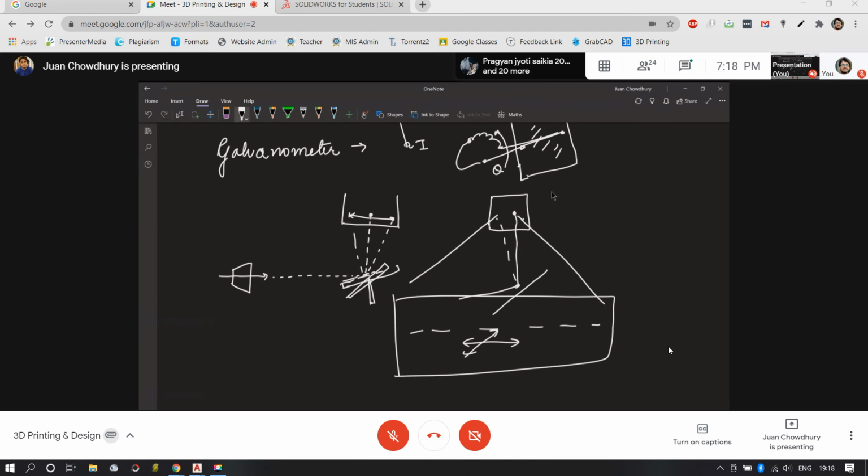So you can understand how surface texture is relevant: I can move the laser so precisely that the surface roughness or the staircase effect in printing is almost negligible. That's an important point, and this is an advantage of the SLA process.